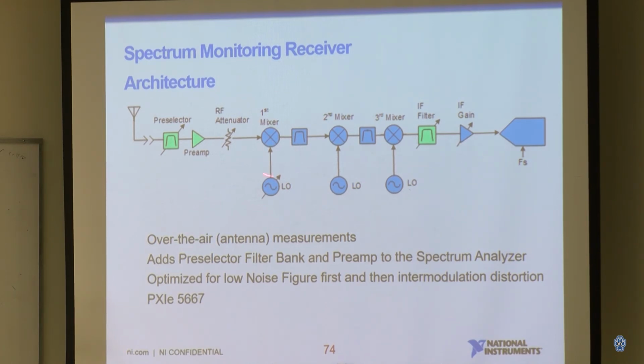And think about trying to analyze signals from 1 gig up to 20 gigahertz. That means your pre-selector needs to be able to tune from 1 gig to 20 gigahertz with a certain amount of bandwidth. It's a really expensive component, and they are pretty sizable. They could be really big. So it's a challenge. You need to find a good one and an affordable one in your design.